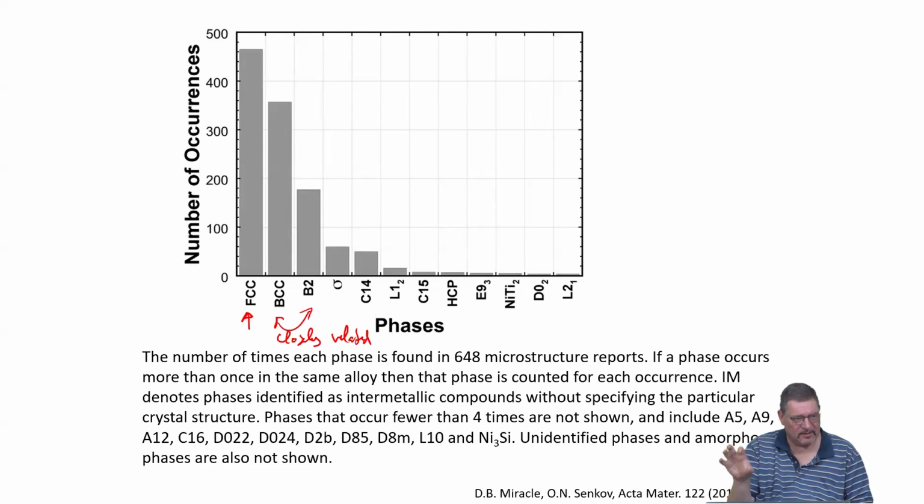And is the crystal structure, especially close to the melting temperature, of that additional element also close to or even identical to the crystal structure which the other alloying elements form? If that is fulfilled, this is maybe an excellent choice for trying whether you really get a solid solution.